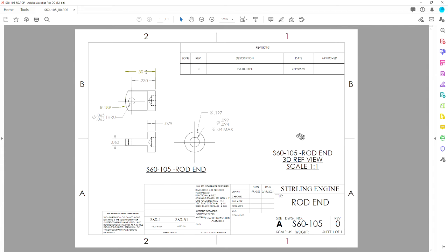Okay, so the important dimensions we have here is the 300 thousandths long with a radius of 0.189 on the radius, which corresponds in the diameter of the width of it being 0.197. So we need those three numbers to start our base feature. Alright, so let's go to